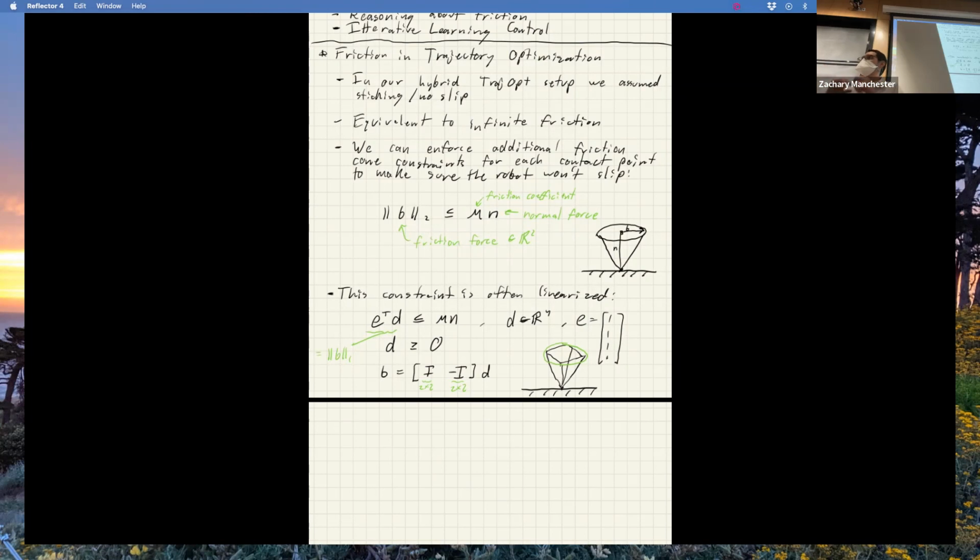They're not as fast and robust, and there are fewer options. There's pretty much only one decent open source SOCP solver. It's called ECOS. Whereas there's a bajillion QP solvers, and everyone's very used to using QPs for control. Been doing that for decades, right? So this is a pretty standard trick so that you can set this thing up as a QP, basically.